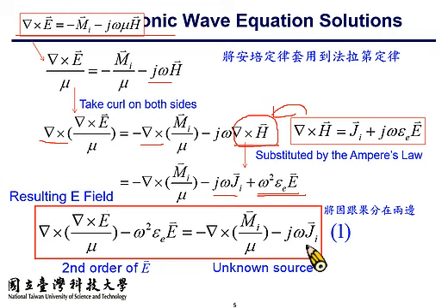However, the production of electrical field intensity is through the time derivative of J. You know the j omega term. So that means as long as there is a time difference in the amount of impressed current, it will induce electrical field intensity E. And on the left hand side, you see that the first term is the curl of E. So you take the spatial derivative of E twice.